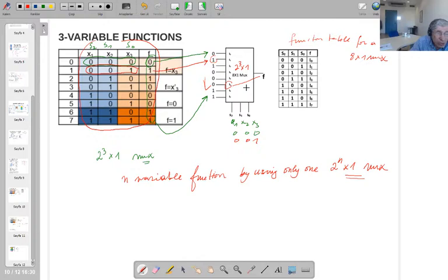The reason is that if you're going to produce 1 million of a function, if you're going to do a production of this, you need 1 million of those. Then you've got to use the SSI design, because in the SSI design, the number of gates that you're going to use is going to be minimal. So the cost is going to be minimal.